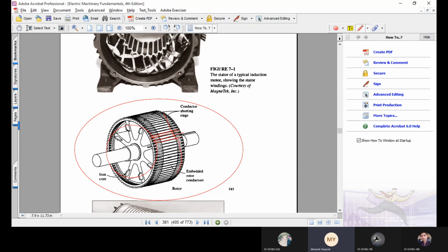But the disadvantage of this construction is that when we have finished with this squirrel cage, we can't add any further conductors to it. So once this machine has been designed or manufactured, it offers a fixed EMF and can operate for a fixed load.